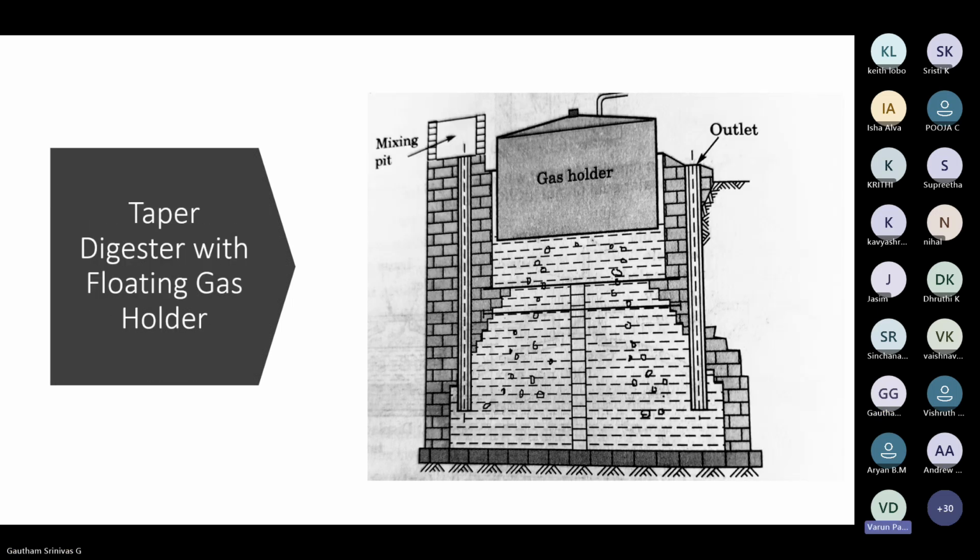To increase the volume? Not the volume itself, because like I said, it's the same. If the water table is high, or if you're going to higher altitudes where you have to install this, you can't really dig very deep. Mountainous terrains, for example. So you just have to make do with whatever depth you can go to. If you have this kind of design where the width is increasing, the depth can be reduced in that case.